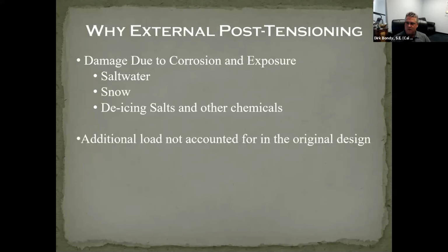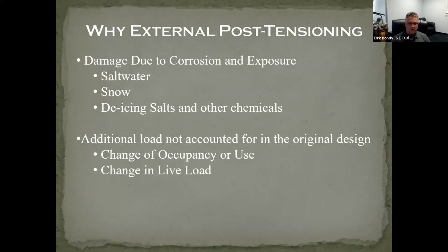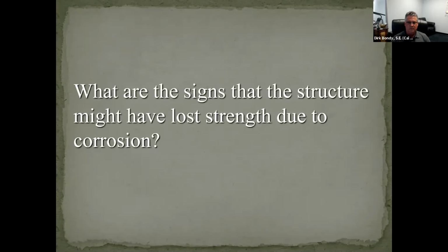There may be additional load not accounted for in the original design. That has happened to us. Landscapers come along and add a lot of landscaping load. Soil can be some of the most heavy load that you'll ever apply to a building. A change of occupancy. The architect may want to change the occupancy of the structure, so the live load changes. Topping slabs, landscaping.